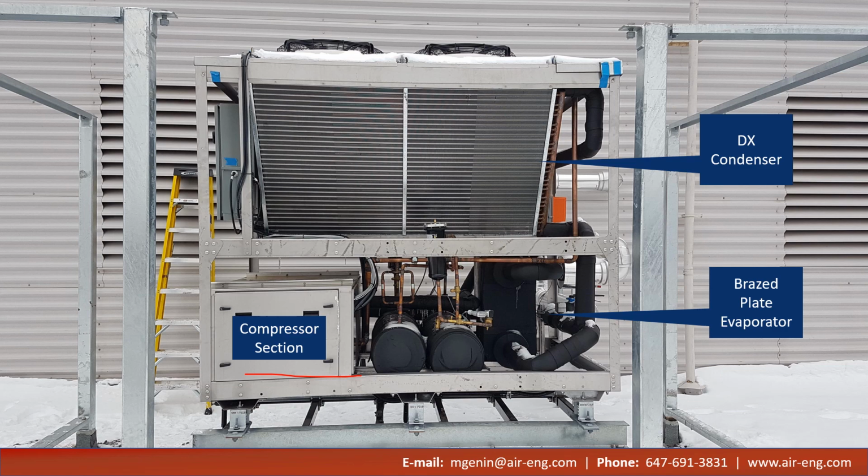In this example, we also have these insulated cylinders. So they're probably not condensers because they're insulated. We also don't have any water piping going to them, but I can tell you in this case they are what are called liquid receivers. And we can cover that in the more advanced Refrigeration 102 seminar.